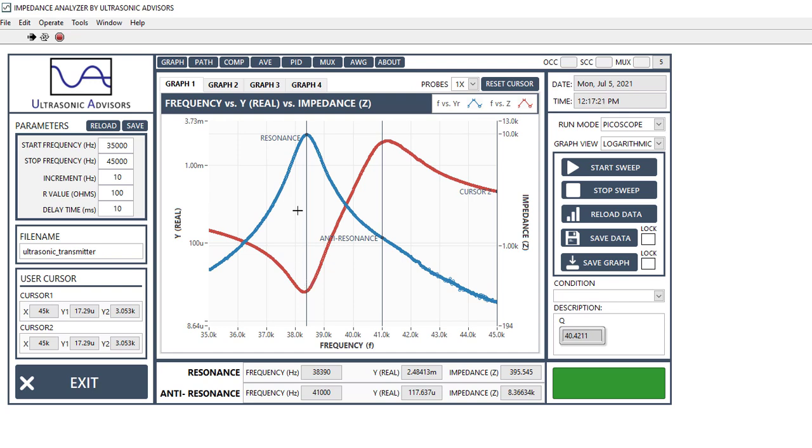So the real admittance is only measuring the response of the LCR circuit, because that's the only part of the circuit which has power dissipation. So needless to say, when we want to characterize and understand the resonant frequency, we look at real admittance, which is basically voltage to current, or voltage to that current, which is in phase with voltage, causing power.